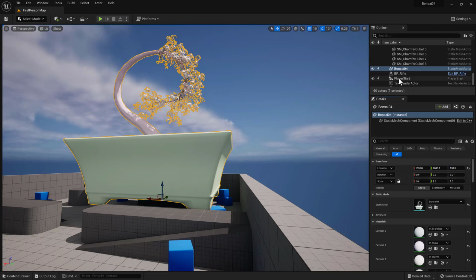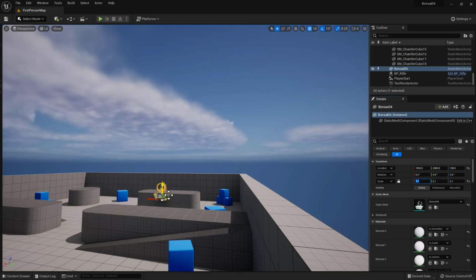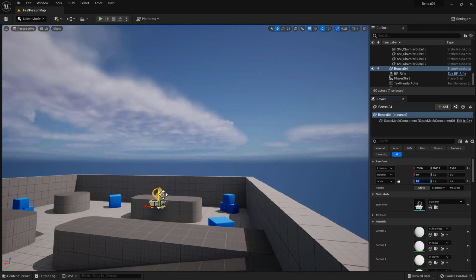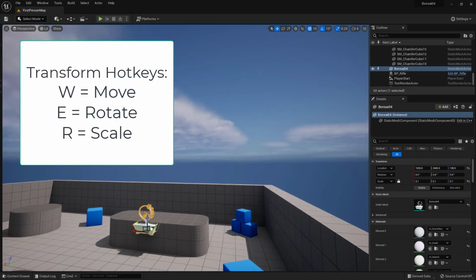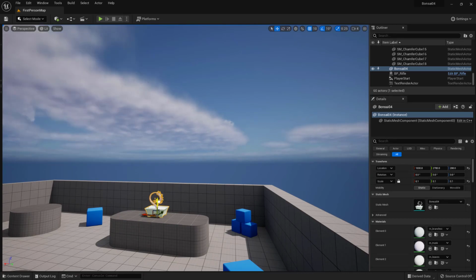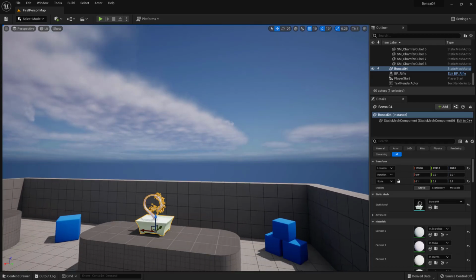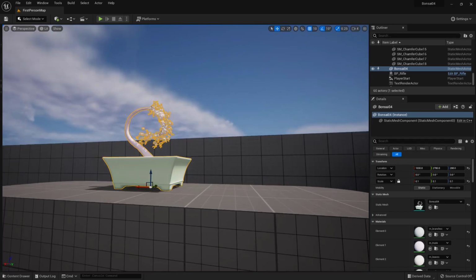You see we have that selected in the outliner, and I can lock the scale and just change this to 0.1, and there we go. That's more realistic. I remembered it coming in super small before, but maybe I did something differently this time. I don't know. Anyway, that's up to you.